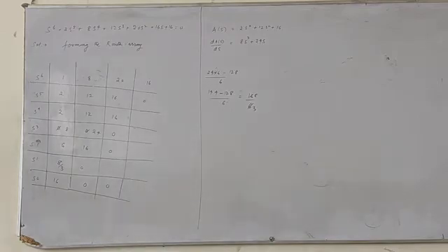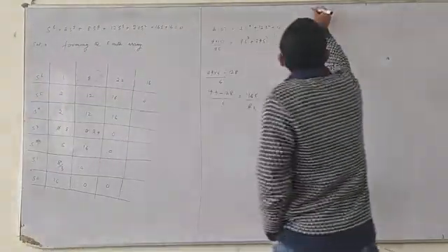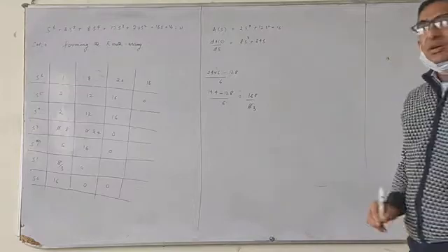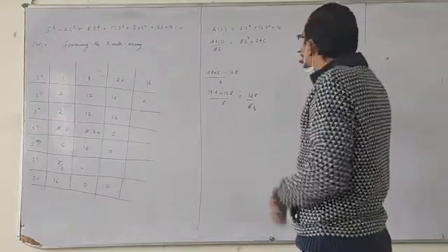Next, since there are no sign changes in the first column of the entire Routh array, hence there are no roots in the right half of S plane. And the system under investigation is a stable system. Okay. Now let's have an auxiliary equation now. This is not asked in this question, but sometimes may be asked in the GATE examination. Normally this is asked.